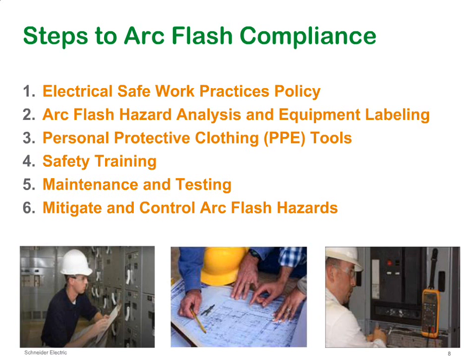It's a very important subject, and it has to be recognized that part of the general duty clause in OSHA requires the owner of the facility to provide a facility that's safe and free from hazards that could potentially injure or kill his workers. That extends to the fact that just putting a label on the equipment and then requiring people to wear a tremendous amount of clothing and do tasks that are not associated with that would not fly, basically. So some mitigation has to be performed, energy levels have to be reduced. And that is the last step of this that pertains to the arc flash analysis.